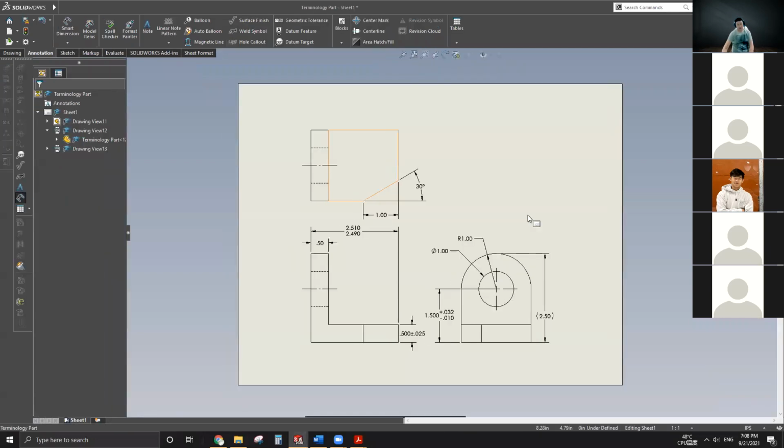And the drawing for this one, okay. This is most likely, I'll say, the best practice of how to machine this part. So this is the machine drawing of this part. All the hidden lines respect all the hidden features. And since it's a through hole, there is a center line. And for the missing corner, identify an angle and a distance, which is enough to identify how big this corner is.